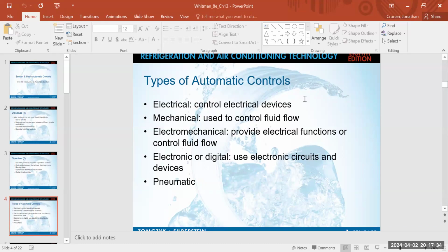So the electrical side is us creating electromagnetism. The mechanical side is that plunger being pulled into the valve. So even though it's electrical, there is a mechanical action within that relay and within that contact. Your gas valve is also considered electromechanical. If you have a solenoid valve, that is electromechanical.